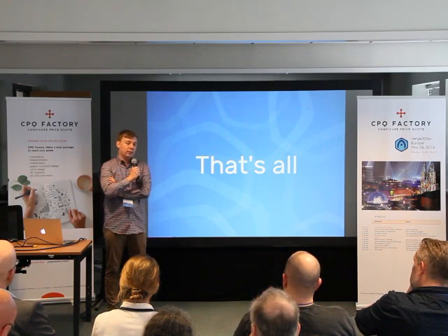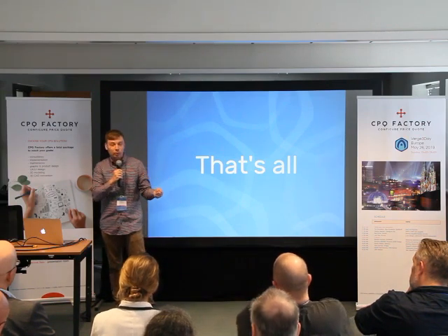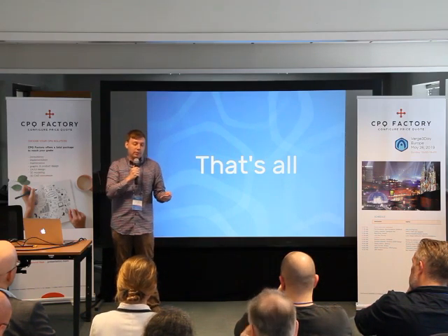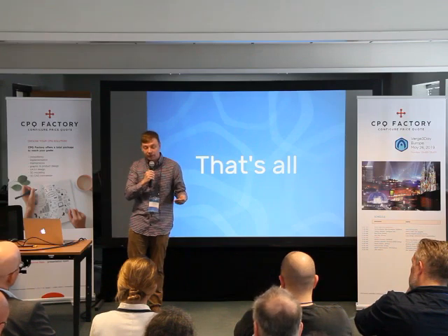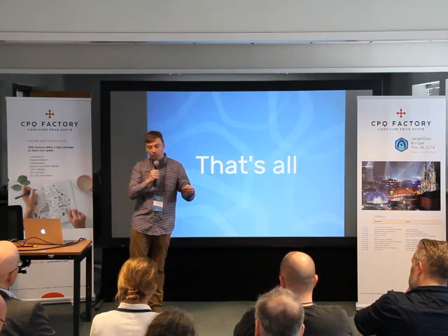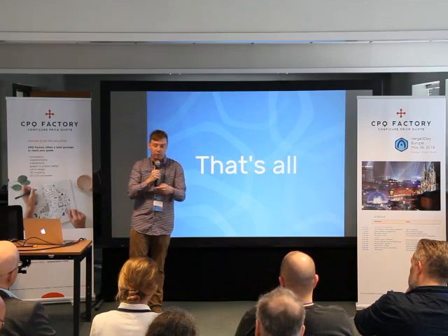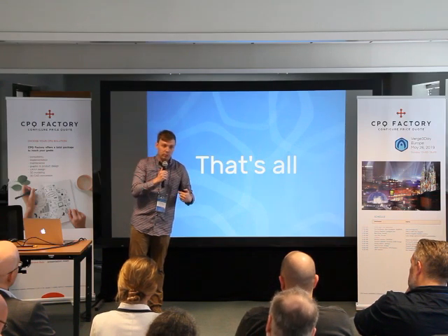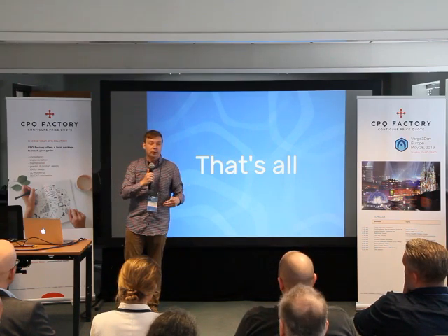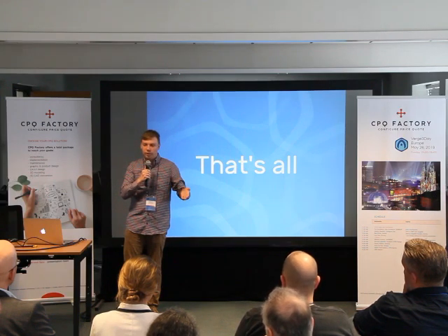Yes, you can combine simple shaders. For example, you have a simple glossy shader for chrome material and a material for plastic. You can just connect them to a mix shader and use a special puzzle to set the value, changing this value in the mix shader, and very quickly switch between these two materials. Then you will have two materials. You will economize in shaders, and in the speed of changing between them.